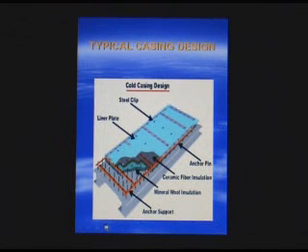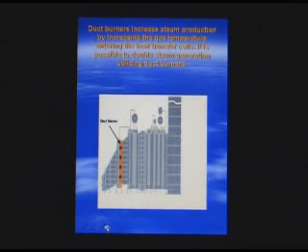Shows a cold casing design with the various layers of insulation to keep the external temperature at a reasonable level. If there's a duct burner, it's usually put at this point. It will basically augment the waste heat recovery gas to maximize the steam production.